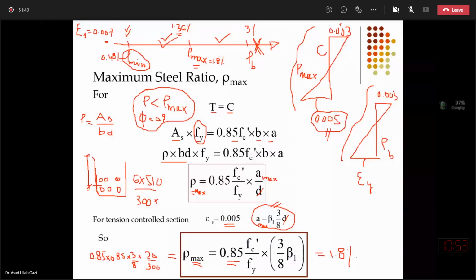But when you have 2 layers, the centroid of the steel will further move up, so you may get the distance from soffit to the center maybe at 90 millimeter, roughly speaking, or maybe at 100 millimeter. It depends. We will discuss how much would be the clear gap between the layers, and then we will calculate based on first moment area principle where is the centroid.